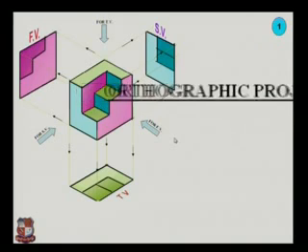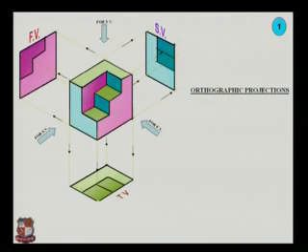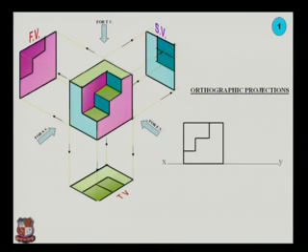It is the side view. Now we will see the orthographic projections of this 3D object by considering the first angle projection method. First of all, we will draw the XY line. Above the XY line we will draw the front view. As we had seen in this form, it is a front view that will be drawn above the XY line.